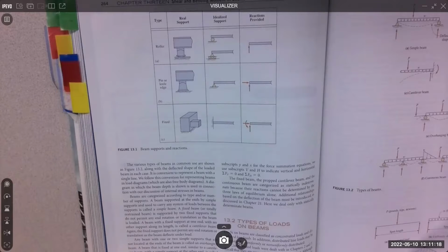The statics does go internal to the beam, where in statics class we didn't go there, right? We just stayed external to the beam. So you kind of got to do a little beam analysis in statics before you go off and determine bending moment. Once you get bending moment, that's the internal force inside the material, then we can get bending stress. And that's our goal, okay?